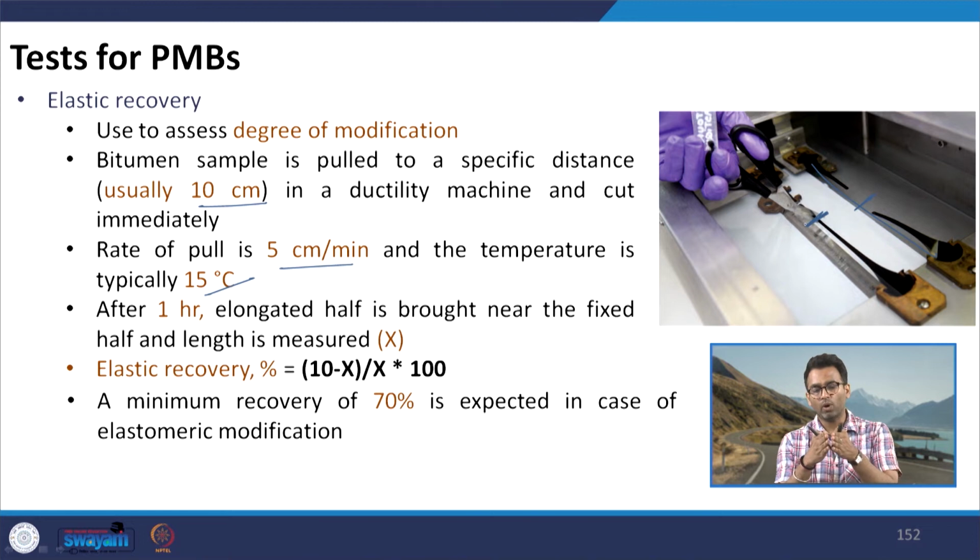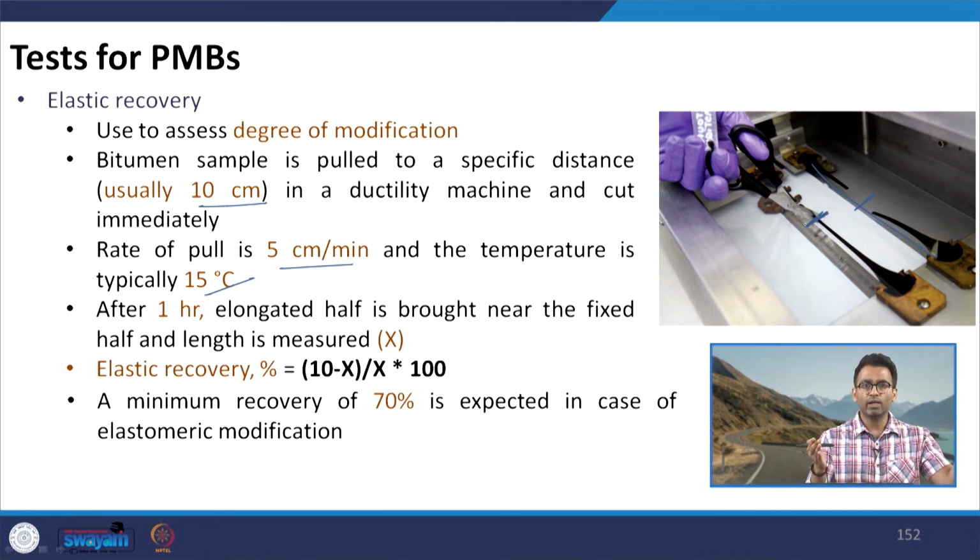Alright. So, after 1 hour, of course, since this is a polymer modified bitumen, we will see that this cut portion has again tried to recover. So, what we will do, we will bring this end closer to this end. So, we will bring the elongated half near the fixed half, and then we will measure the length.